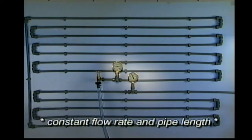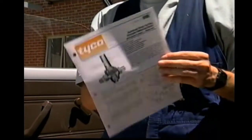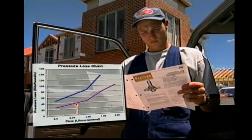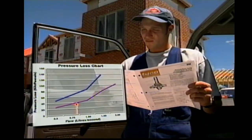Fittings and changes of direction cause extra pressure loss, just when you least need it. Valves and other equipment also cause pressure loss at various flows. Fortunately, the manufacturer usually supplies a fitting and flow performance chart.